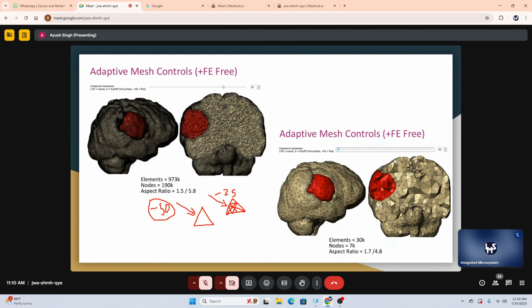And once we have increased the number of triangles, we can assign a different property for each triangle. Similarly, the smaller the elements, the more accurate the model would be, though the efficiency of our calculation would be lower.